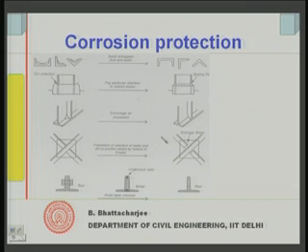If air moves, the moisture will go away, vapor cannot deposit, and therefore corrosion protection will be there. In fact, what you have done is provide a gap; this was earlier completely joined here with a fillet weld, as you can see. Now, if you leave it slightly up, air can move easily, and therefore there is no moisture vapor condensation here, and drying off is easy.